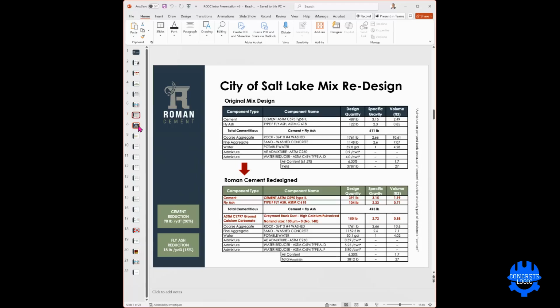And you'll see the results. And the results confirmed what we said, that this limestone is behaving differently. Even though it's limestone, it is behaving quite differently because of the particle packing effect, the lower water demand effect, because it has much lower surface area, and the way that it's able to volumize the cement paste as a micro aggregate. It still works.